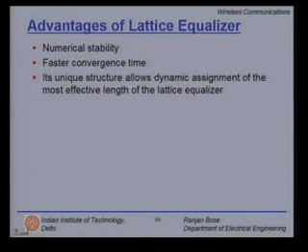Its unique structure allows dynamic assignment of the most effective length of the lattice equalizer. This is the first time we are talking about the effective length required for the equalizer structure, which should be matched to the delay spread of the channel.